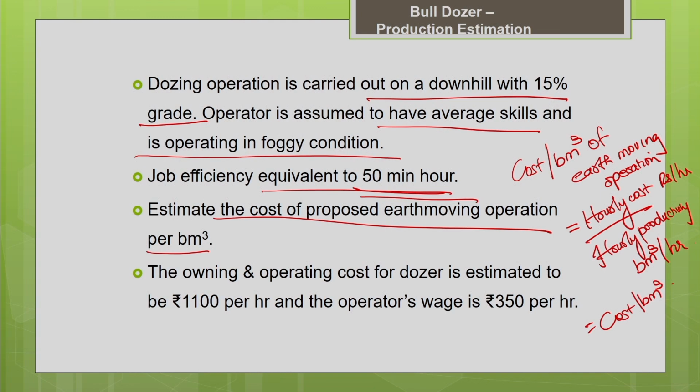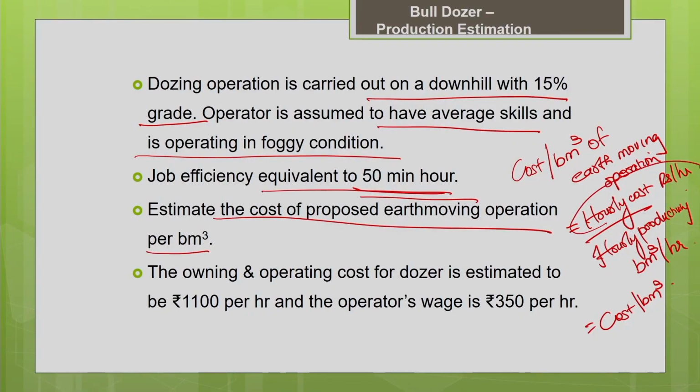This is a very important parameter which we use when you plan for a bid. When you go for unit rate contracts, you need to know the unit cost associated with every activity. We need to make an accurate estimation of the unit cost of every activity. For that you need the information on the cost associated with the machine and the productivity associated with the machine. That also forms a part of the unit cost.